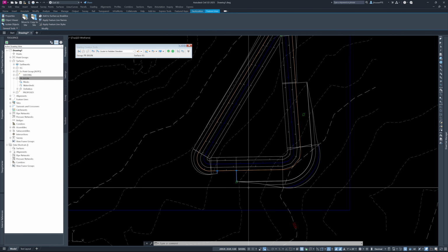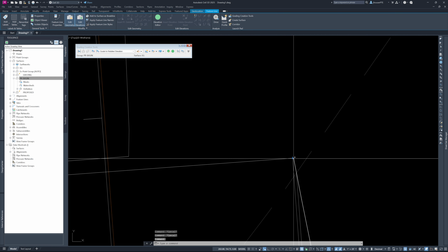I guess what I should have been saying is, if you used this one, it would be hard to drag that one because there's just a very small area. But you could move just that outside 3:1. If there was a reason why you needed a 4:1 slope or some other percent slope, you would have to pull that one back, and then you'd put another grading object in there. All right.